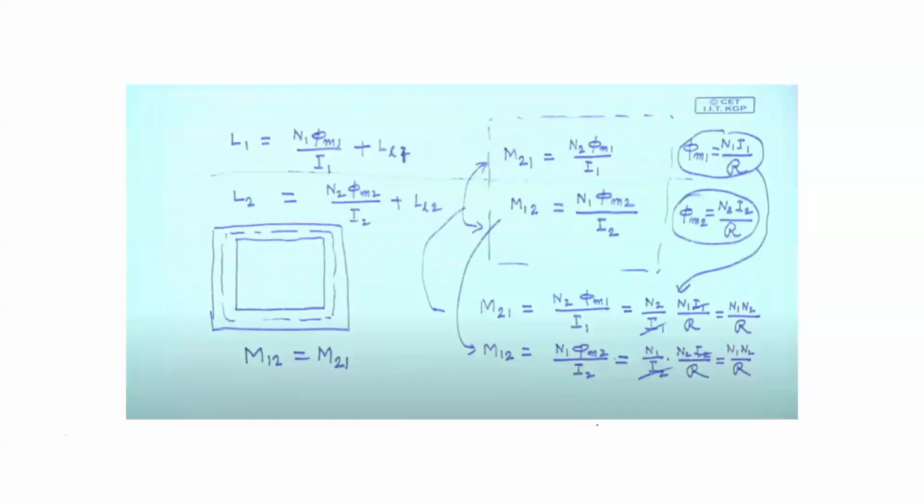Okay. So now he will try to find out what this mutual part is. So for finding the mutual part, let me go here. He's saying that M21 is basically the mutual inductance, oh sorry, I'm mistaken. What I'm saying is that M21, where the first 2 means the mutual inductance in the secondary winding due to the current flowing in the primary winding. So the second position denotes the current in which winding.